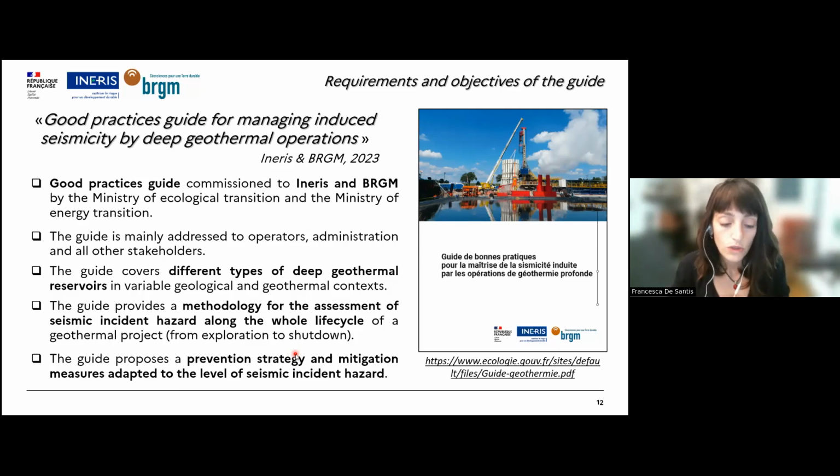And with this guide, what we try to provide is a methodology to assess seismic incident hazard along the whole life cycle of a geothermal project, so from exploration to shutdown of a site, and also to propose prevention strategies and mitigation measures which are adapted to the level of seismic incident hazard of the project.